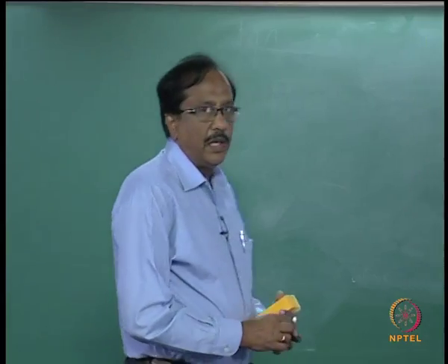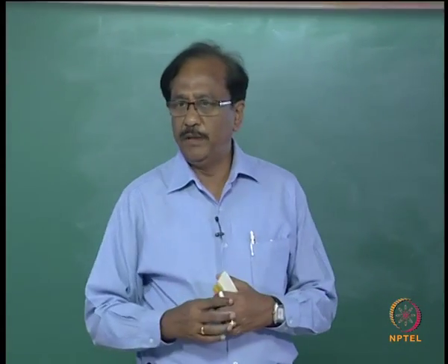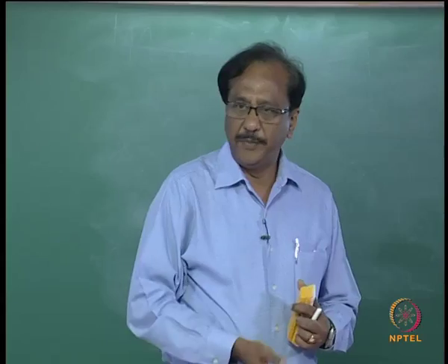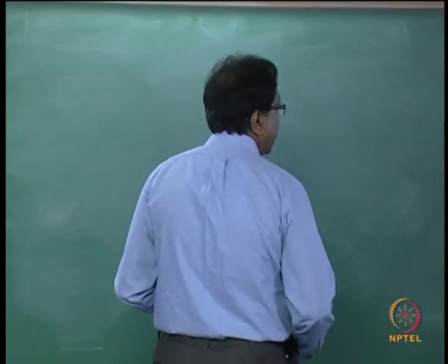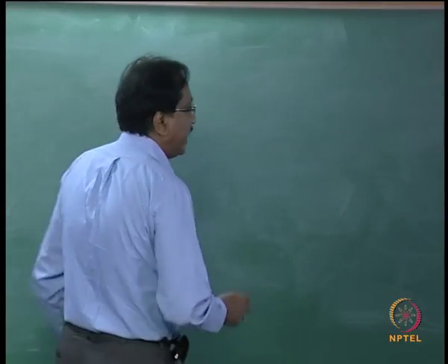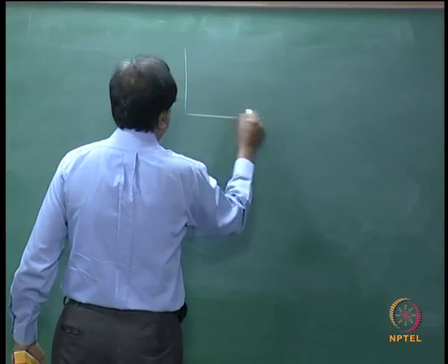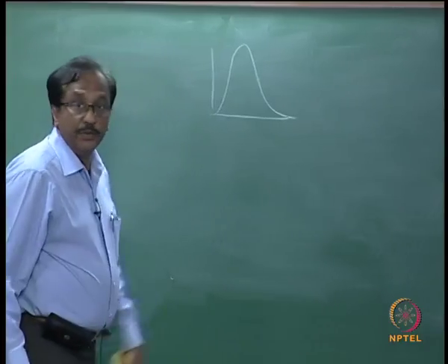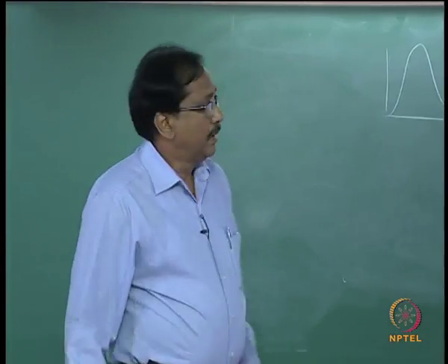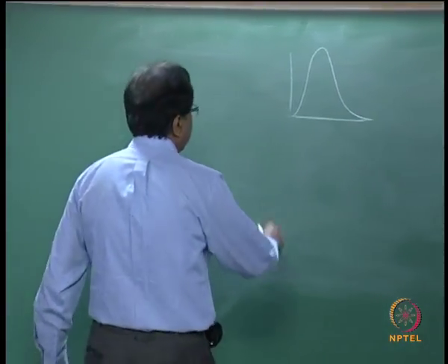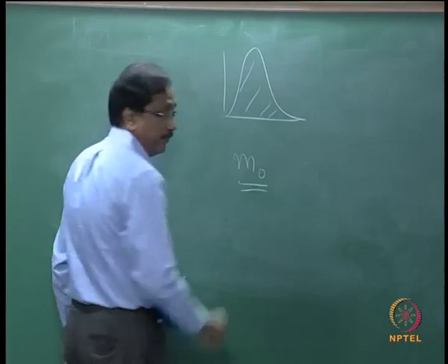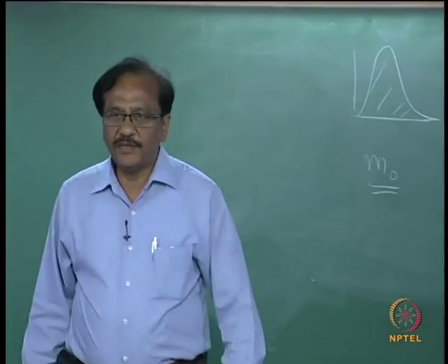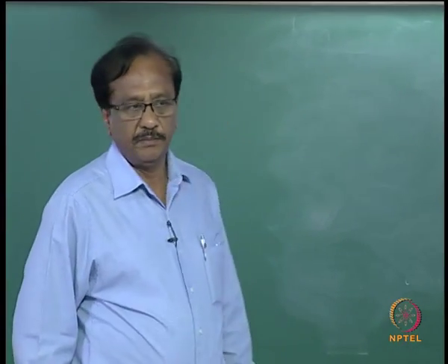So when you write a program on your own, for example, to check whether the spectral density estimates are going to be correct, you have the spectral density curve using the formulation. You just find the area under this curve, which will be m0, referred to as the 0th spectral moment.